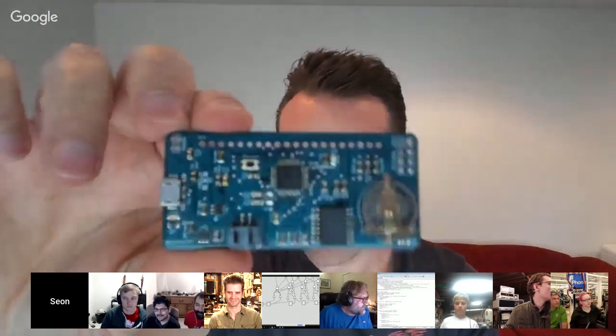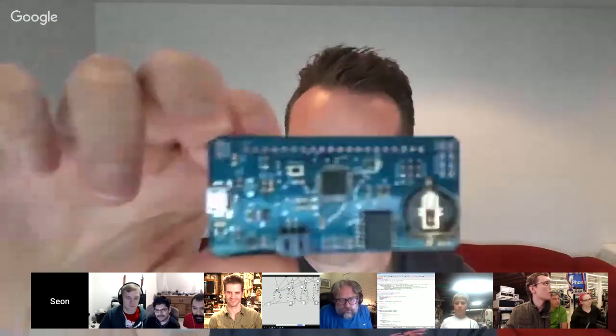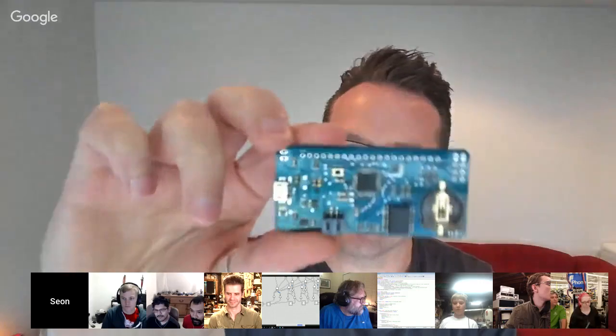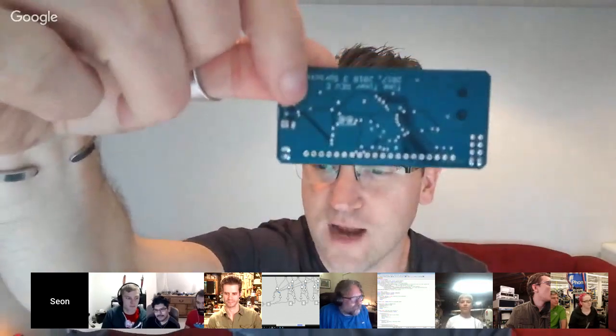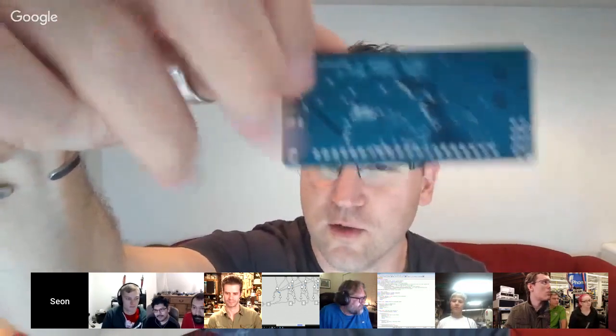Unfortunately, I ordered the wrong Schottky diodes and the wrong size crystal, but they're being delivered today, so I'll be able to finish this board. And of course, I forgot to put a header on it to program the SAMD21. But I did put the pins on the back, so I'm going to just hand solder those for the moment and use Atmel-ICE to program my chip. I have no idea if this board's going to work. It probably won't. It'll probably blow up in my face. But that's okay. It's a learning process.